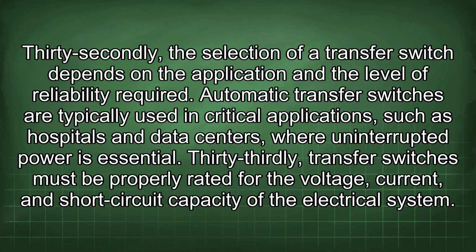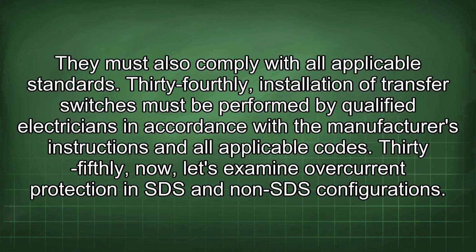Automatic transfer switches are typically used in critical applications, such as hospitals and data centers, where uninterrupted power is essential. 33rdly, transfer switches must be properly rated for the voltage, current, and short circuit capacity of the electrical system. They must also comply with all applicable standards. 34thly, installation of transfer switches must be performed by qualified electricians in accordance with the manufacturer's instructions and all applicable codes.